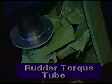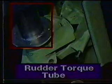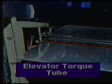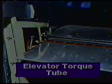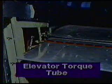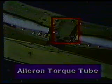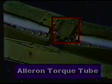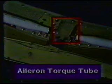The large tube attached to the rudder structure is called the rudder torque tube. The large tube attached to the inboard end of each elevator is referred to as the elevator torque tube. The tube that attaches to the aileron bellcrank or bow tie and connects to the aileron push-pull tubes is called the aileron torque tube.